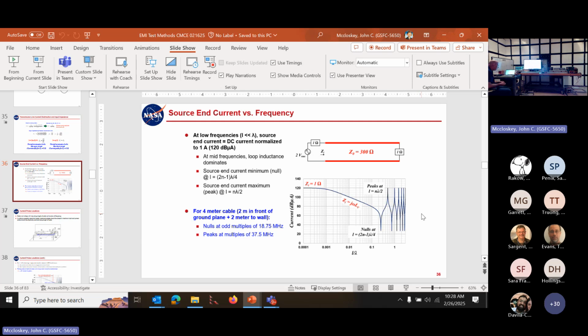And while it's always ideal to come to EMI testing with flight-like cables or even flight cables, ideally, people almost never come here with the actual flight cables. So the next best thing is flight representative cables. And the emphasis there is primarily on cross section, twisting, internal shielding, and particularly shield terminations.